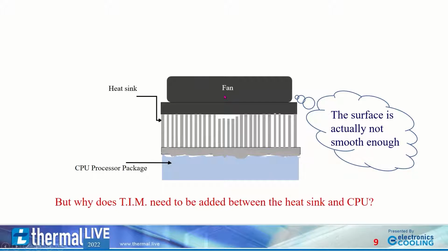When these holes are filled with still air, the still air will be a heat insulator because its thermal conductivity K is the lowest, 0.024. Therefore, a thermal interfacial material with high thermal conductivity is needed to fill these voids instead of still air.